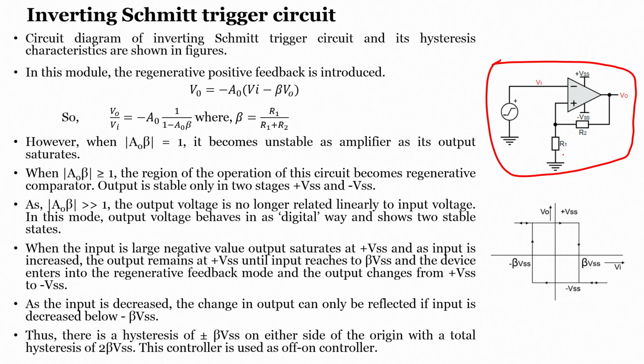When it goes to plus VCC or minus VCC depends upon the resistors R1 and R2 that we choose, and on the plus VSS and minus VSS. Here we will see a brief understanding of the inverting type of Schmitt trigger circuit and its simulation, and once the simulation is done, the results will be compared with the op amp circuit built using a TI board.